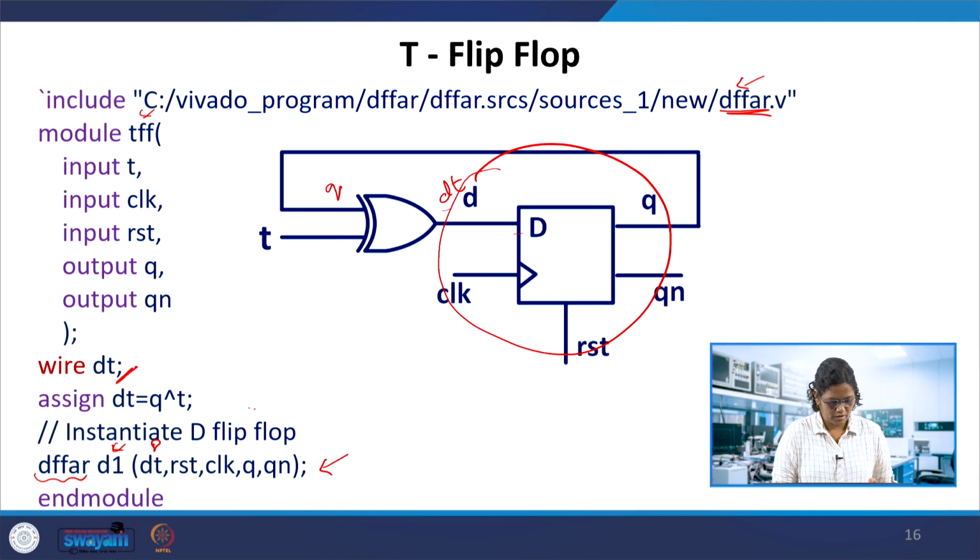This is over here, and assign this XOR gate, two of them. Anyway, the D flip-flop instantiation was done with the always block. Now Q and T give the DT output. The wire should be declared as wire here. There is no other declaration like reg, because those are covered in the D flip-flop asynchronous reset module.